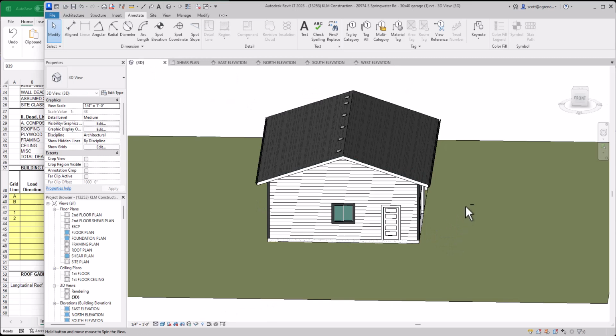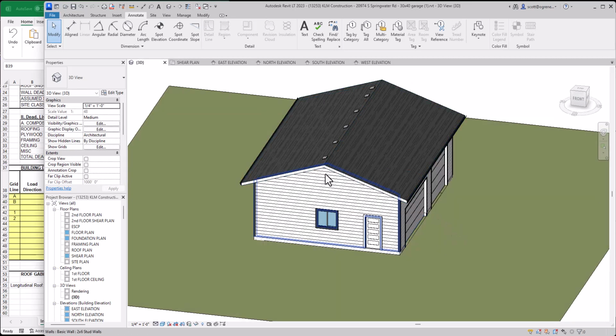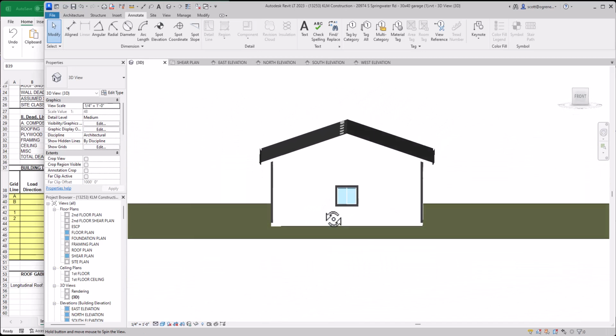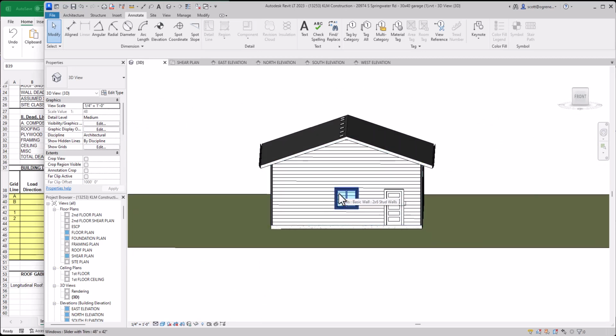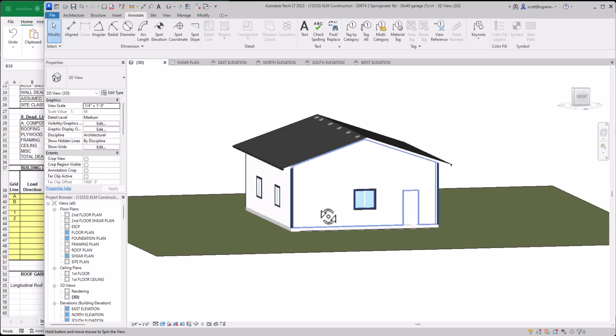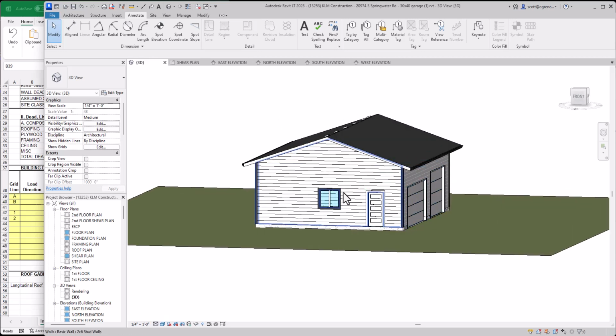The longitudinal direction is generally assumed to be the long direction of the building, which is almost always the direction of the main ridge. And the longitudinal direction is as if you are looking at the building along the longitudinal axis. So in this case, we're looking along the longitudinal axis, and this is the rear wall, as we can see, and then this is the front wall.